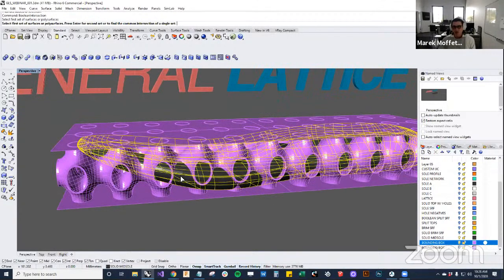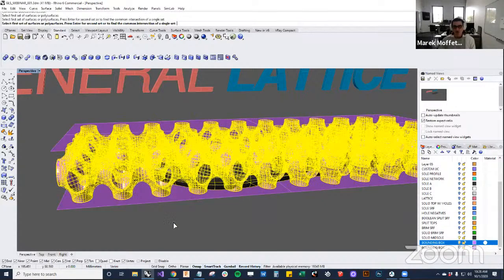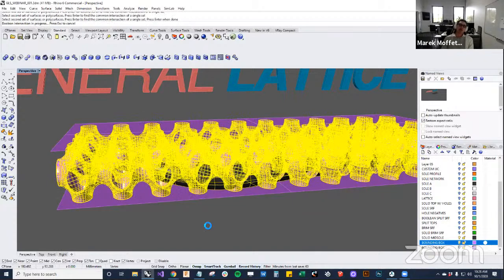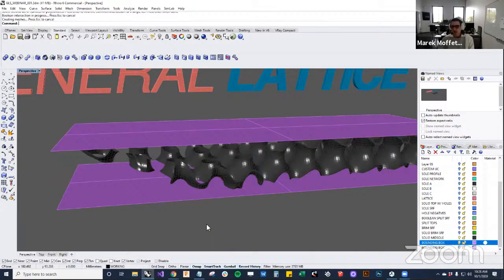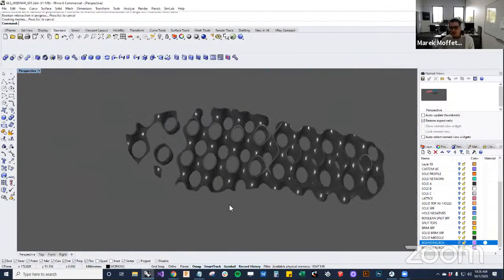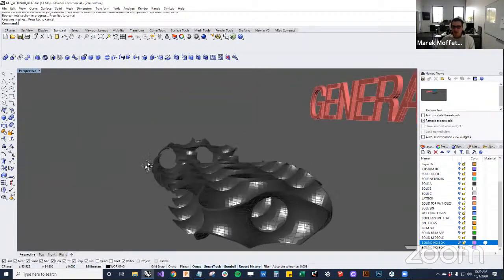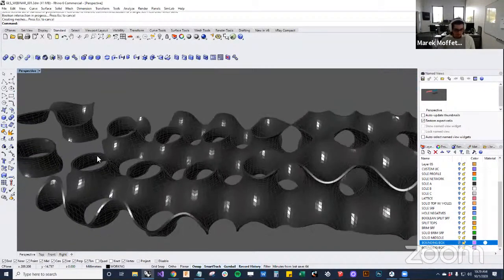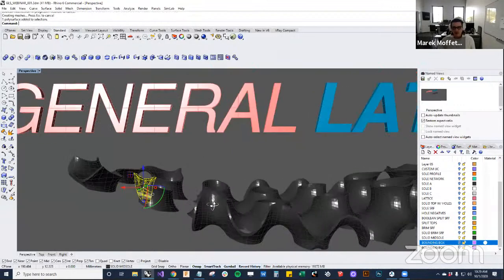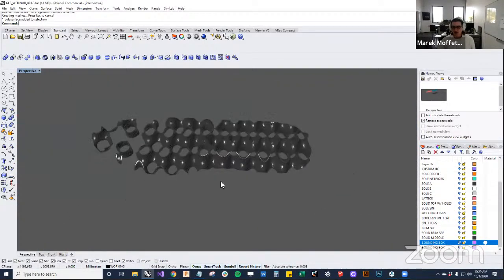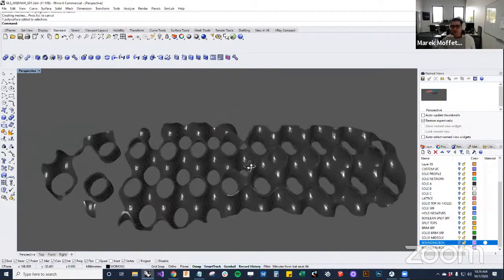And you can select your polysurface, the closed volume, and then the polysurface lattice and hit enter. Oh, I apologize. First, select your first set, hit enter, select your second set and hit enter. And now the intersection is working. And again, depending on the complexity of your parts, depends how long this can take. But you can see, I wanted to show the potential benefits or not of this technique, is that, again, depending on your geometry, it can create a lot of unwarranted instances. So for example, we have sort of a floating shape here, which could easily be deleted or joined to something else, but you don't have as much control over creating solid voxels because you're cutting away those voxels. But again, nonetheless, still a really useful technique.